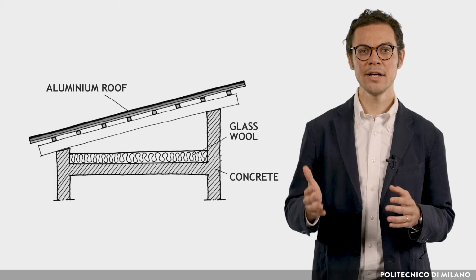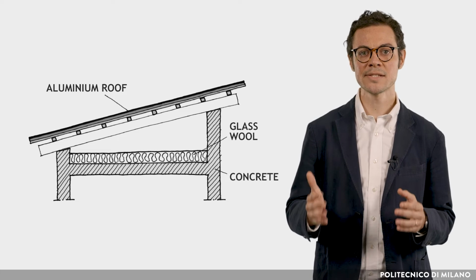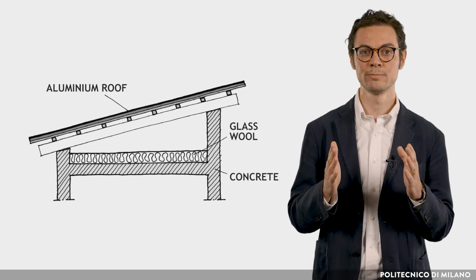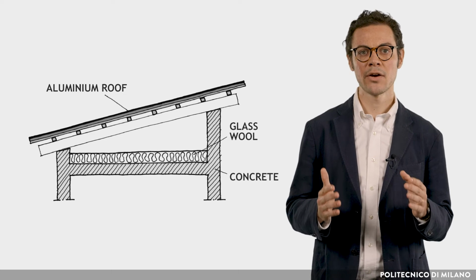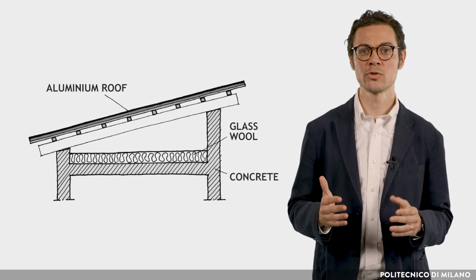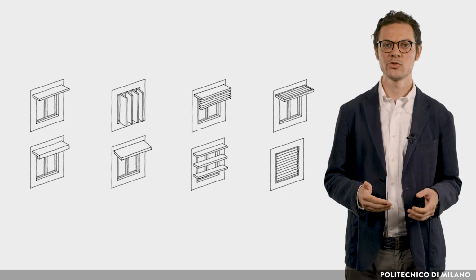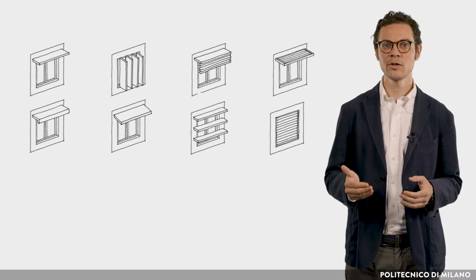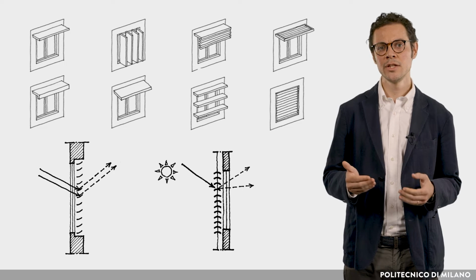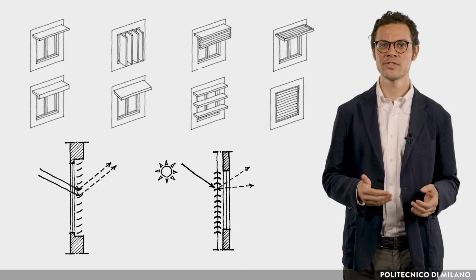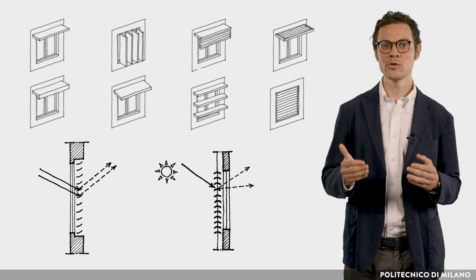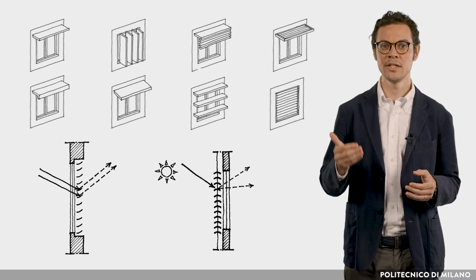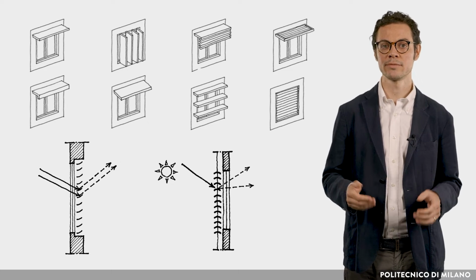Roofs can be light or heavy, but they must have a good insulation value. Medium weight walls, floors, and ceilings are recommended for the best exploitation of solar passive gains. Regarding windows and ventilation openings, devices for sun control are necessary in order to keep out the sun during certain hours of the day. Note that they should be also adjustable to let sun in when it is required.